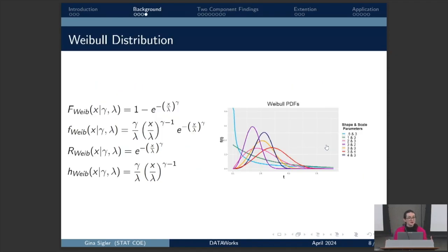Okay, so a little bit about the Weibull distribution. So you can see the crazy spaghetti plots that I made up there. The light blue one on the side there looks like the exponential distribution. And I kind of mentioned this. So a lot of times in reliability, you end up measuring things as an exponential distribution, usually for ease. But the problem with that is that it is making an assumption that you have a constant hazard rate, right? A constant rate of failure, no matter what happens. And it has this independence built into the background. And as we discussed, that doesn't really work for this scenario because there's dependence between my 2 turnbuckles.